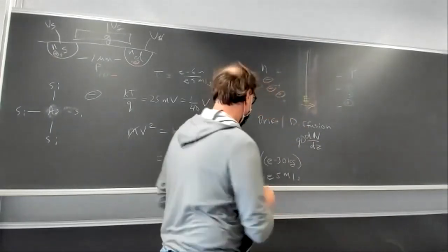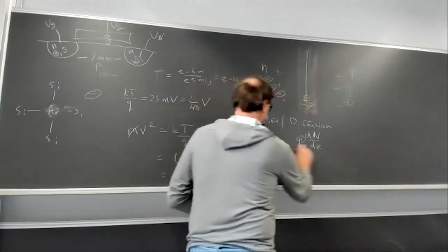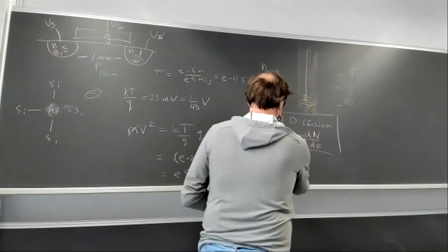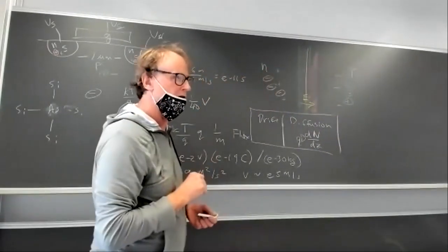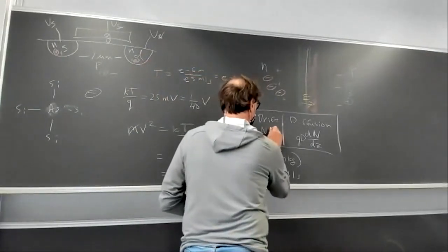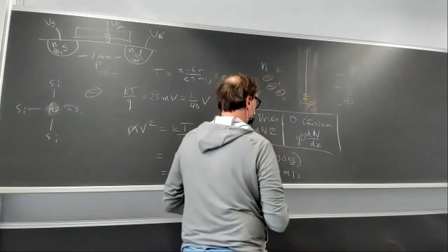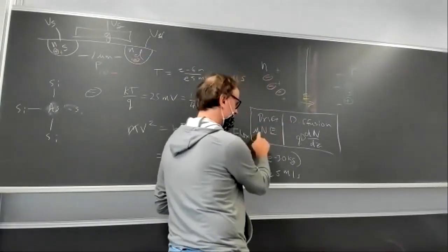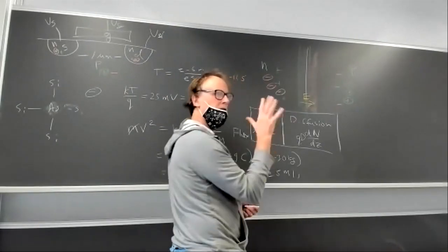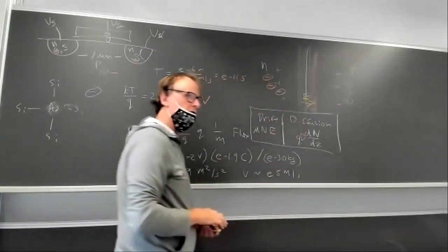That's the flux, or the current density, due to drift and diffusion. Due to drift, there'll also be a current, but that current is proportional to the charge density times the electric field times something called mobility. It's just another constant. It's proportional to the amount of charge density times the electric field, for small electric field. These are the two mechanisms of current flow.